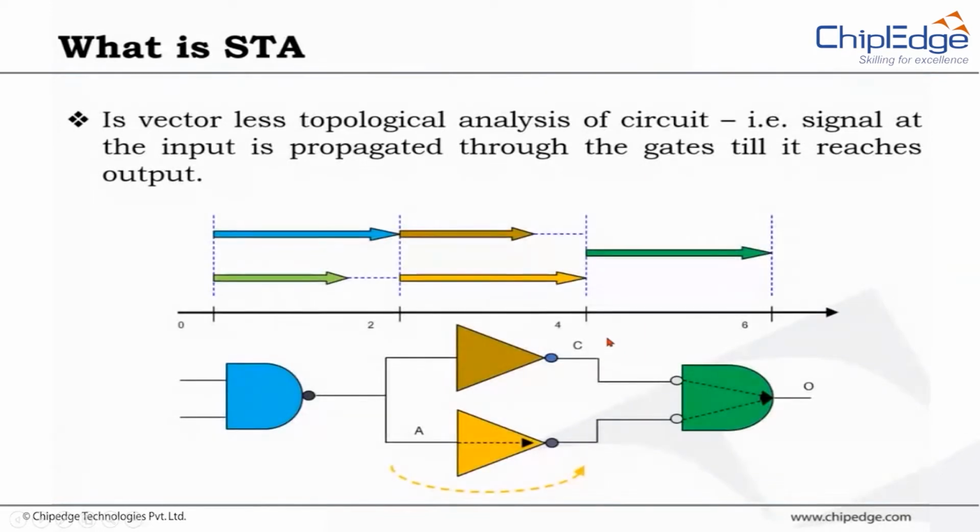So look at this picture here. Now you have an AND gate here, couple of inverters, and then going to another AND gate kind of structure with inverted inputs. Now there are multiple paths possible here. So the static timing analysis tool understands these paths. That is, for the first AND gate, there is a path from one of the inputs to outputs, another input to output. Again, from this common point, the path can go through the upper inverter, path can go through the lower inverter. Again, at the destination gate here, at the third gate here, input to output possibilities are there.